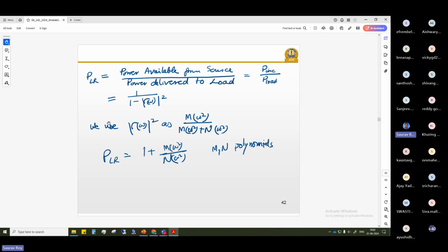So the one difference you must remember, this insertion loss or return loss, they are not expressed in terms of minus. Normally S11 you can write minus 10 dB, S21 you can write minus 20 dB. But when you talk about loss, it actually incorporates the minus sign already.